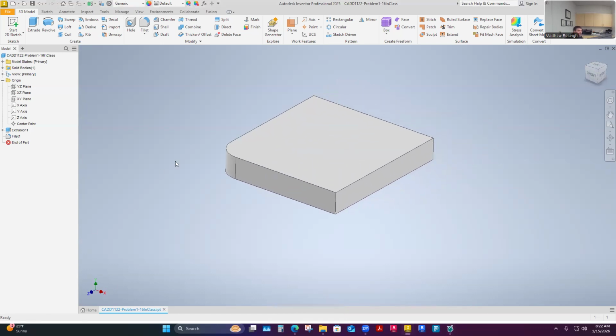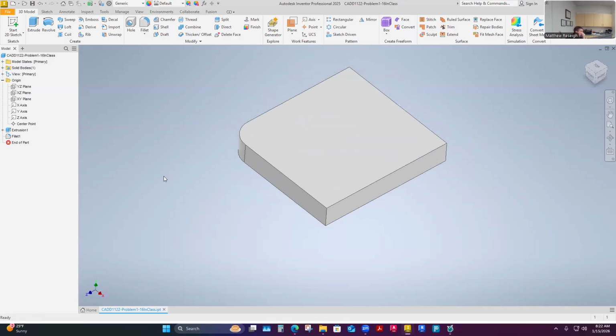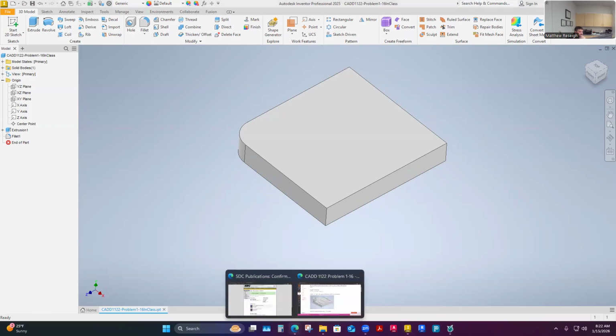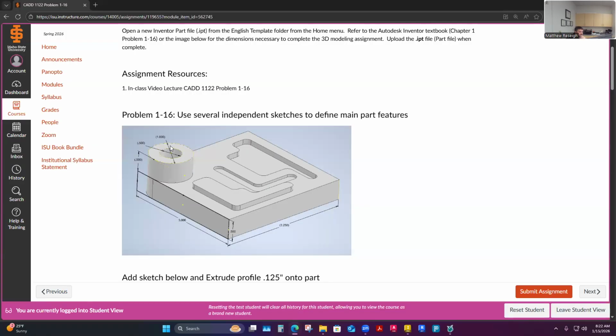And then I'm going to start a new sketch on that top surface there. Just wait for just a second. This sketch will be what? Let's see. Just a 1 inch diameter circle and a 1/2 inch diameter circle.